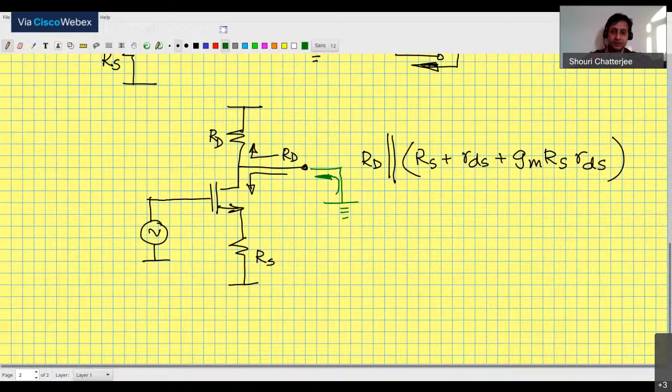Okay. So if I connect this to ground over here, immediately the current through RD becomes equal to 0. So you forget about it. There's no current in RD. Both sides of it are connected to ground, right? And now you have a situation where this is pretty much your situation.